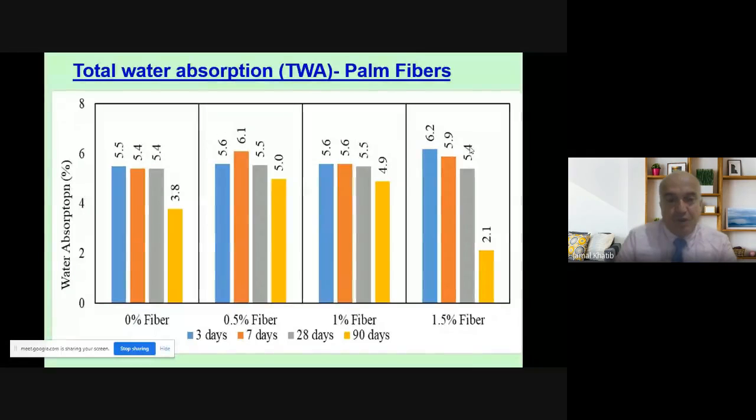If we've got more isolated pores, we obviously cannot measure them using water absorption because there is no open channel to get into the pore. So that is a possible explanation. As I said, we might repeat some of this work in the future. But generally, the trend is a slight reduction in water absorption, but it's not huge.